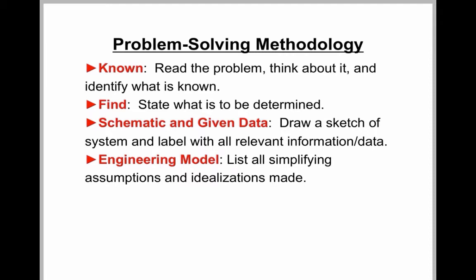You will draw that schematic as a physical concept, such as a refrigerator, but you will also draw it as a thermodynamic type situation. What are the changes in temperature, pressure, enthalpy, entropy? These are all used. And you will develop an engineering model which will list what the simplifying assumptions are.